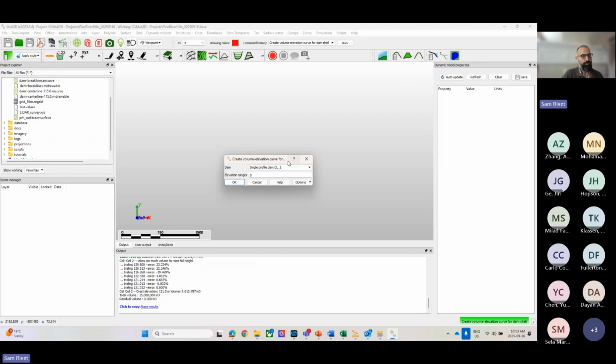All right, so based on this template that I'm using, the same one that we've been using for a while now, 4:1, 50 meters across, 3:1 down, at that reference line location, center line dam. Let me know, okay, from 115 meters in crest elevation to 135 meters in elevation in 10-meter increments, what's my fill volume going to be?